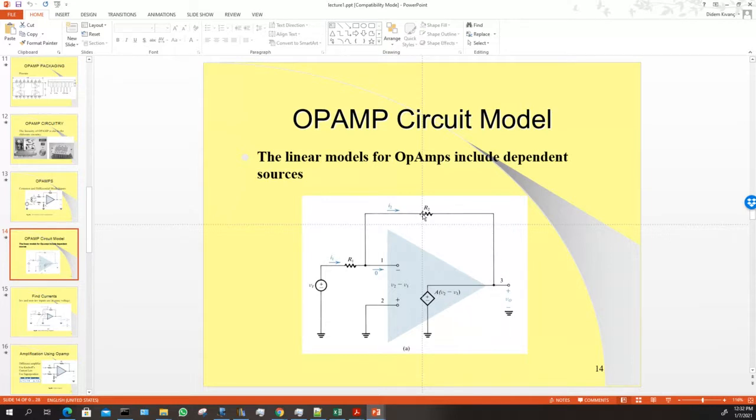Okay? You almost always connect this feedback loop. This is this resistor back in. Because most of the current going over this R1 also goes over R2. The goal of this part is feedback to the op-amp, and it makes the op-amp more stable. If you just applied it without this top loop, you get much higher gain, but the gain changes a lot based on temperature and other constants, and the voltage and everything. So really you need R2 to make the system stable.